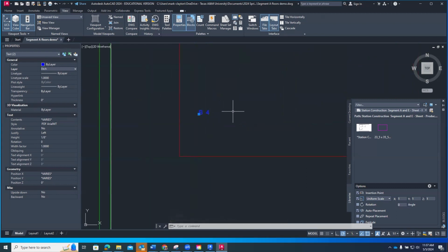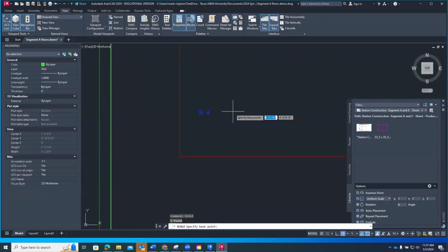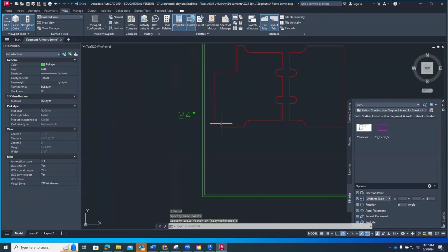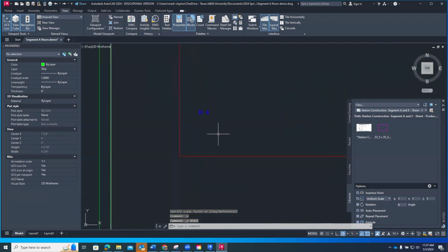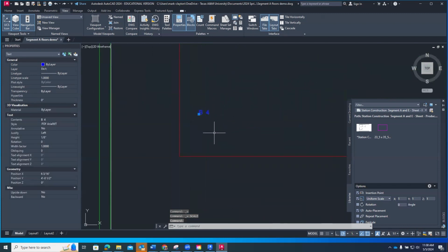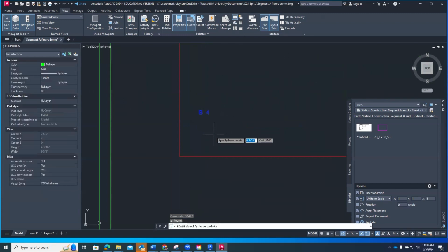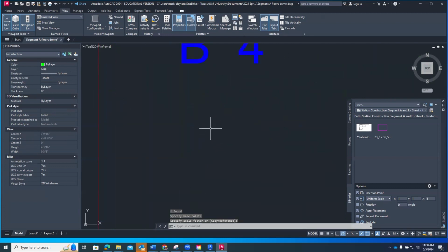So we used a scale command on it. So I will scale, and I can click 2 points just to stretch it a little bit. Nah, that didn't work. I'll undo it, click it, scale it, set the base point right here, and then scale it. So now it's bigger.